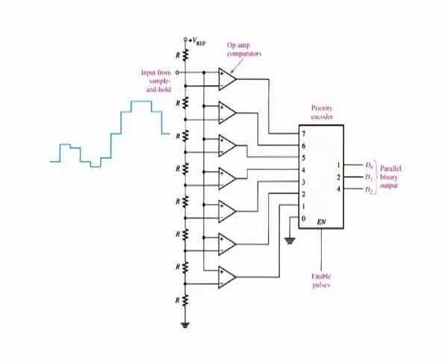A comparator is not needed for the all zeros condition. A 4-bit converter of this type requires 15 comparators. In general, 2 to the power n minus 1 comparators are required for conversion to an n-bit binary code. The number of bits used in an ADC is its resolution.